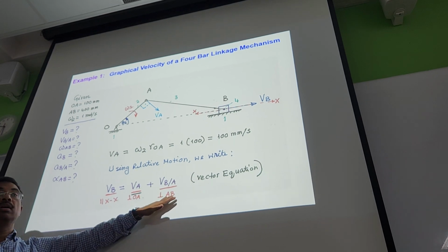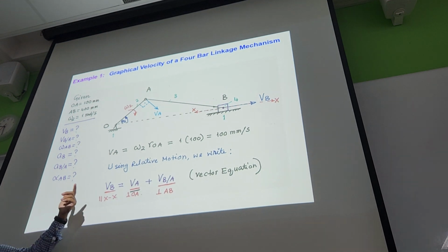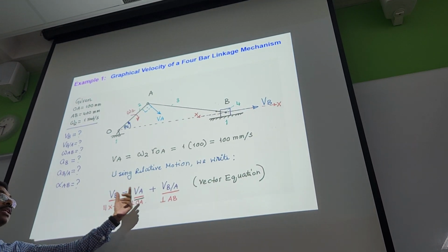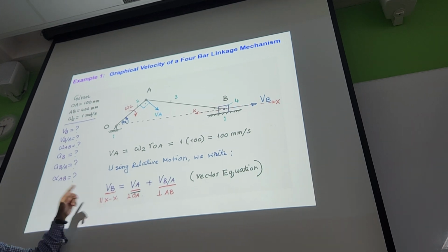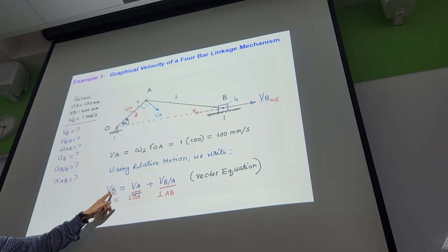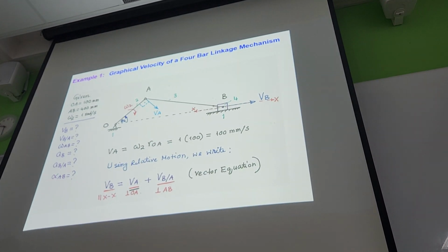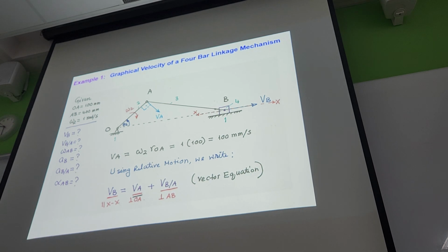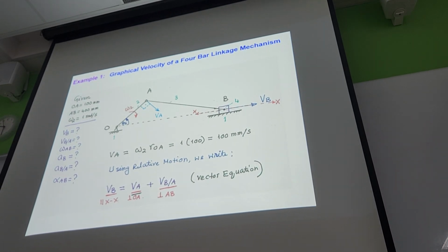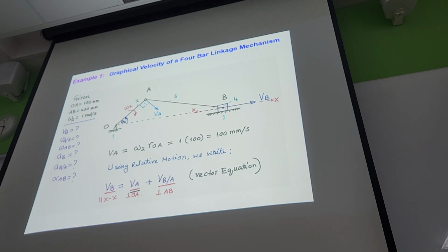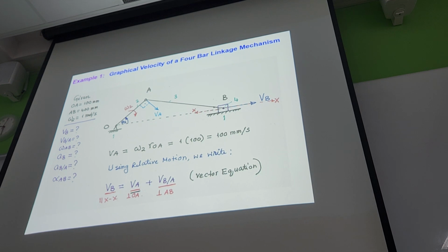So therefore, we said everything very nicely. Everything is said there. So that means this one has an absolute velocity, this one is absolute velocity. Even you can sometimes forget, that's why I said 1 letter index. So our VB and our VA should start from the origin of the vector polygon, it says. VBA should not. But there are some exceptions. We also will be having a problem tomorrow. We'll show you that it will actually have some exclusion, but that is very rare. So that is not our main business. Main business is this one.